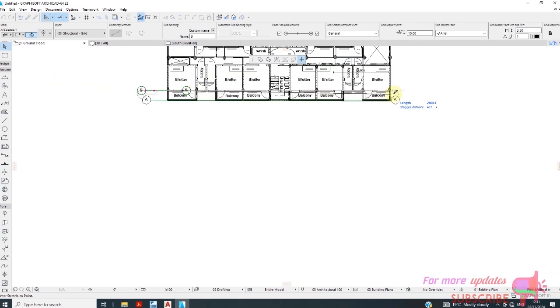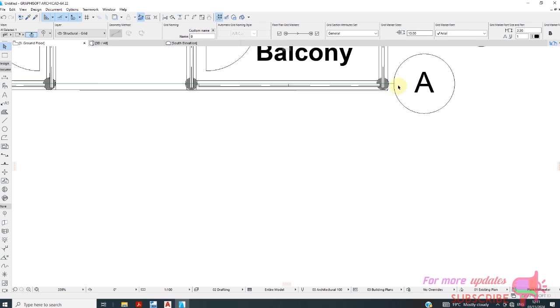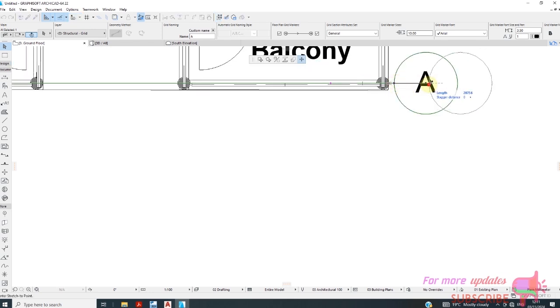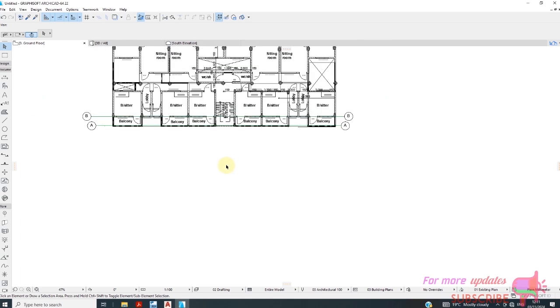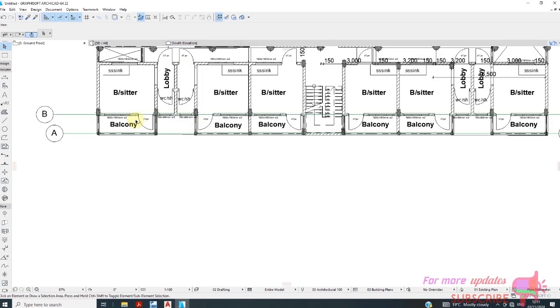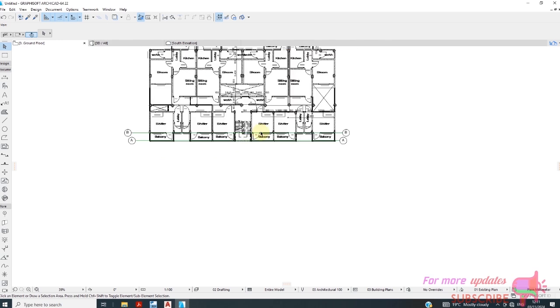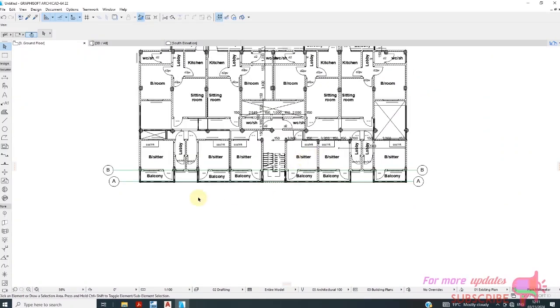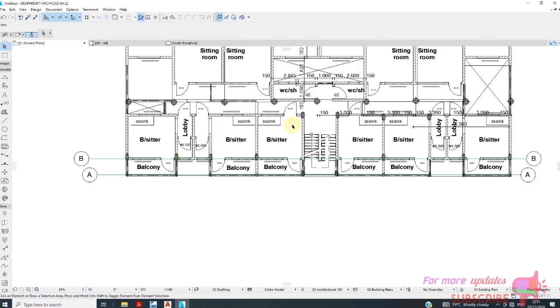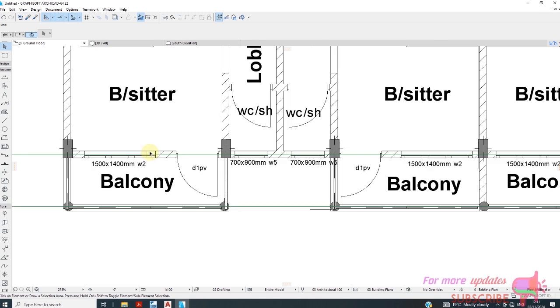So I hope you are following me. If you are using AutoCAD, you can do the same, create those grid lines, and then you'll be able to model. So the thing about Tekla Structure, you cannot assume any grid for now, as far as I'm concerned, because based on the shape and the complexity of this building, if I model beam without grid, I have to solve a lot of validation error, which I want to avoid. So I can repeat the same to all these beams.